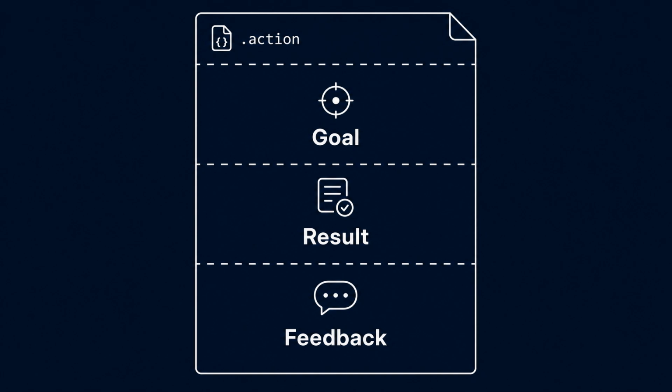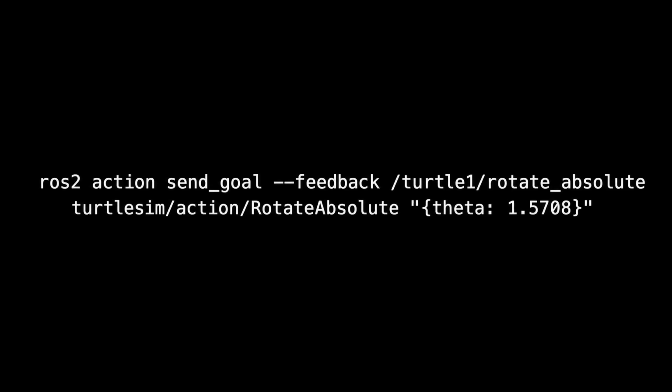Now let's execute an action. We can send a goal using the following command: ros2 action send_goal --feedback /turtle1/rotate_absolute turtlesim/action/RotateAbsolute "{theta: 1.5708}". This value corresponds to approximately 90 degrees.